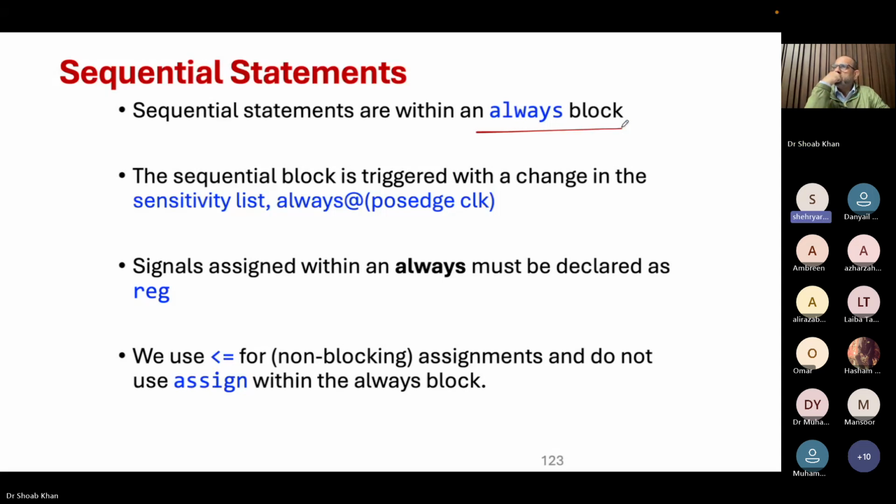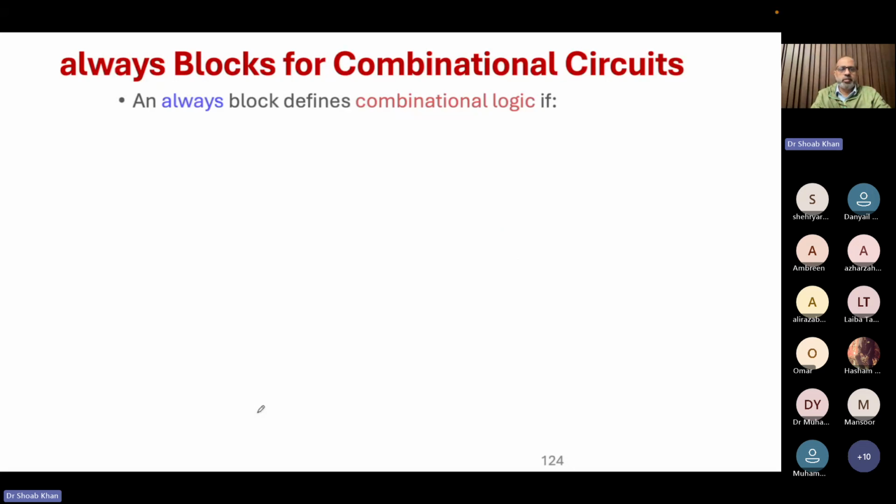Sir, Assalamualaikum. Sir, a question regarding the always block. If you write posedge clock, it's sequential logic, and you always use non-blocking procedural assignment, and do not use assign. Always block it. Assign comes outside the always block.